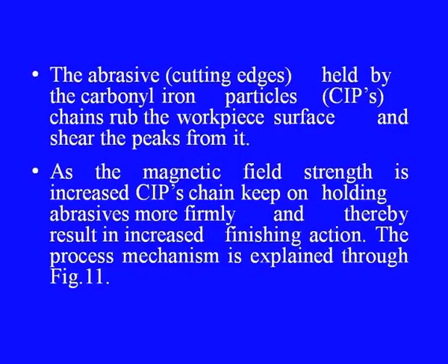The abrasive cutting edges are held by the carbonyl iron particles, which form some chains and disrupt the workpiece surface and shear the peaks from the workpiece surface. As the magnetic field strength is increased, carbonyl iron particle chains keep on holding the abrasives more firmly, and thereby result in increased finishing action.